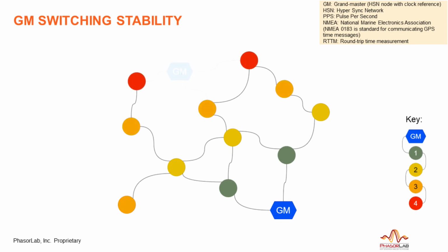If the upper GM node is disabled, its descendants will now select nodes descended from the remaining GM for their own time sources, which increases the number of levels in the network hierarchy to 4 hops in this example. More hops increase jitter in the time, approximately by 1 nanosecond per hop, but crucially a link to global time is maintained, allowing for the disabled GM node to be replaced or repaired without network failure.